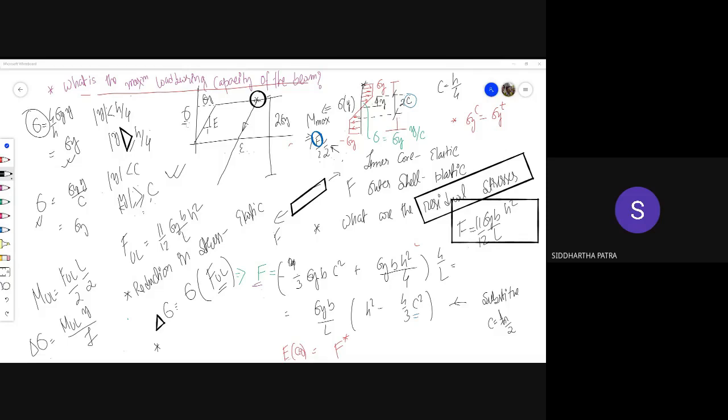And in the second expression, which is outside of the elastic core, from that also subtract the expression that you have got. That would be the stress within the elastic core and in the plastic shell after complete unloading of the beam.